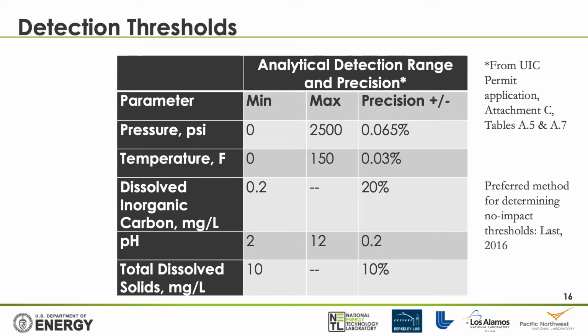However, not all sites have sufficient baseline measurements to calculate no net degradation threshold values. Because no information was available on spatial or temporal variability in pH or TDS for the St. Peter sandstone, the precision of pH and TDS sensors were used to set these thresholds when developing the FutureGen 2.0 aquifer component.